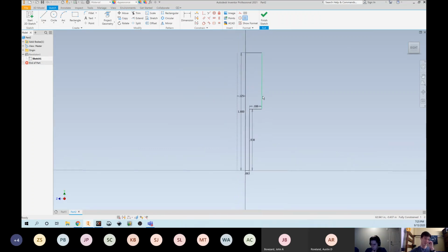So what happened here is I snapped things in place instead of telling the computer how long I wanted them, which means that when I changed this 1.8, this grew along with it. So I have to find where the source of that came from, and it's this first dimension I did, so it's 1.8, and now we're fixed. If I created dimensions properly, maybe that first change would have done everything exactly as I wanted it. That's called parametric CAD. I think we'll get into that next week.